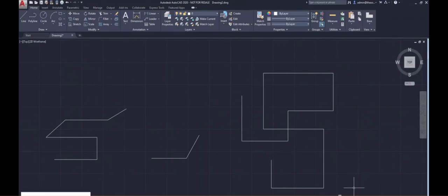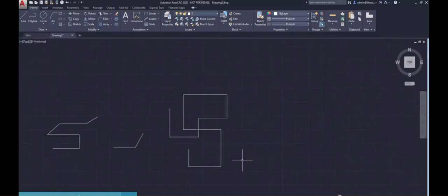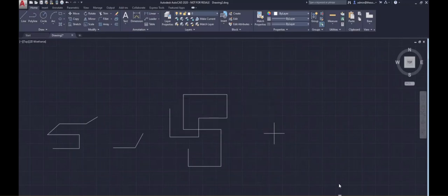Now let's talk about another method which can help you make drawings again pretty easily, and that is dynamic input. So if I go to line command and if I start it, you'll notice that I only have the cursor here, but if you press F12 function key, you'll end up with these extra tooltips. Now this is the dynamic input feature, and right now on my status bar I have it here. So you can just click here to activate or deactivate it, or you can also use its function key F12. So now I've deactivated, it's no longer visible. Now if you don't have this kind of feature on your status